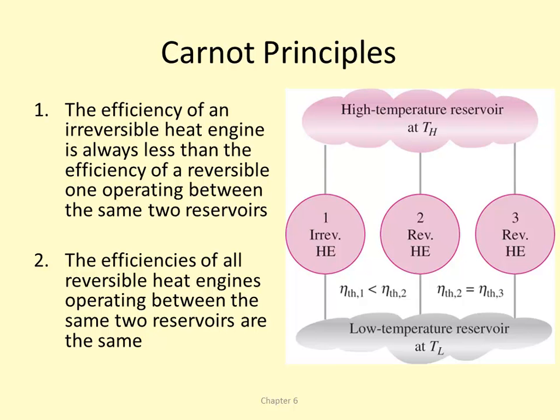But the two Carnot principles are that the efficiency of an irreversible heat engine is always going to be less than that of a reversible heat engine between the same reservoirs. And then all reversible heat engines operating between the same two reservoirs will have the same thermal efficiency.